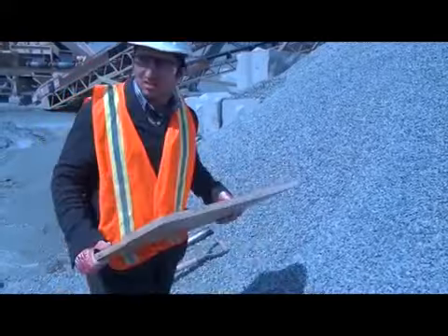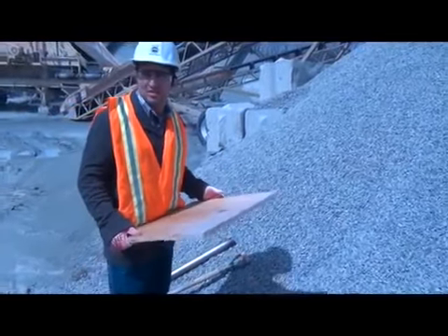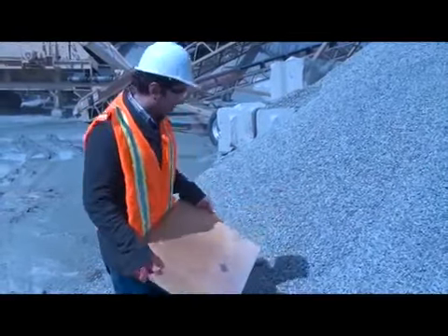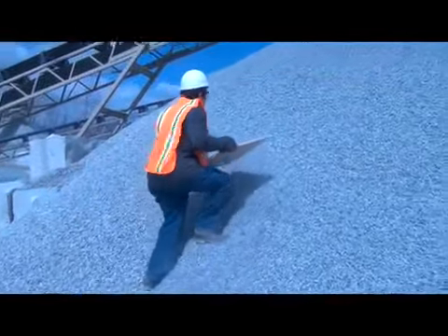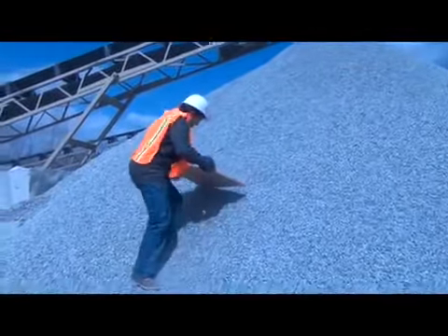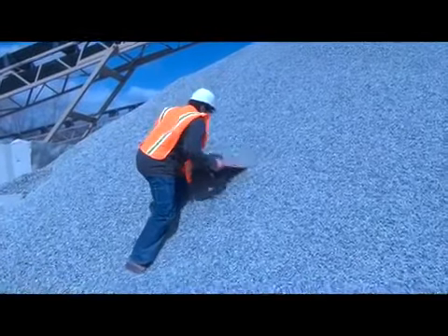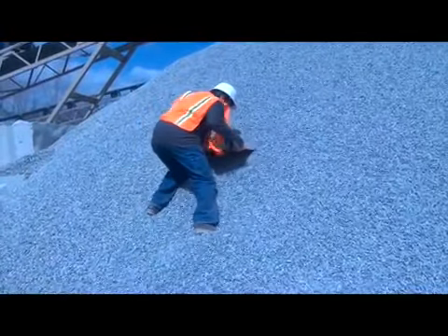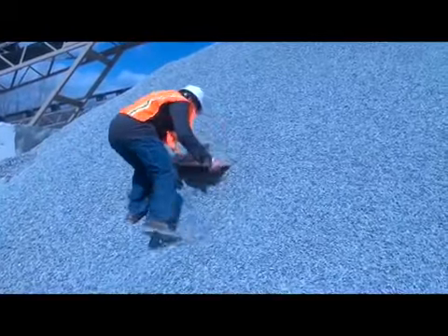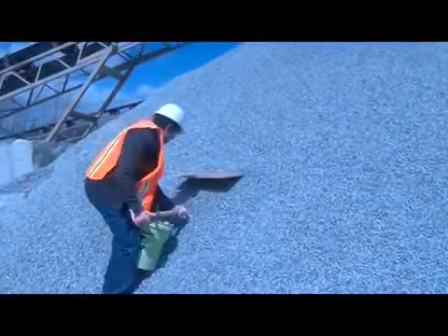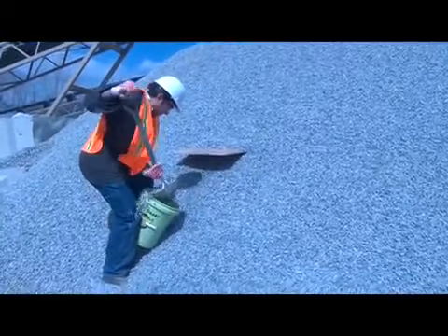When power equipment is not available, samples from stockpiles should be made up of at least 3 increments, taken from the top third, midpoint, and bottom third of the volume of the pile. A board shoved vertically into the pile just above the sampling point aids in preventing further segregation.